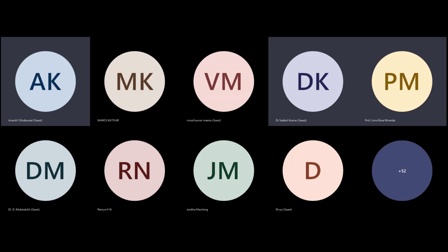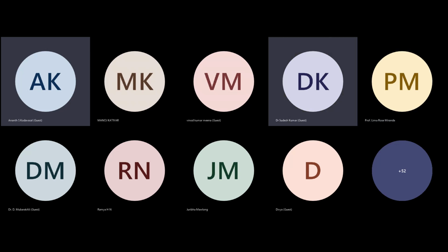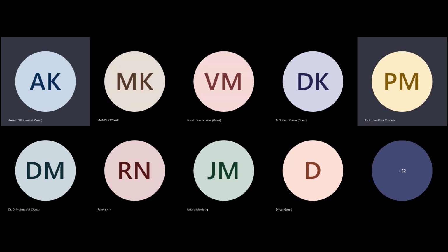In fact, we have developed this technology with IIT Madras. Over 80 samples, we developed the regression based on the turbidity of the treated water. Once you measure turbidity and suspended solids, which is very easy to measure rather than direct BOD and COD, you use the regression equation and get to the COD. That is perfectly acceptable. That's what everybody does the world over.